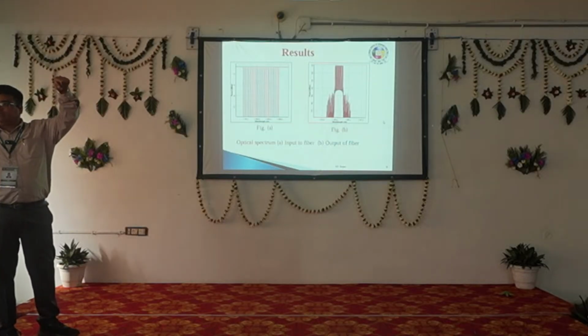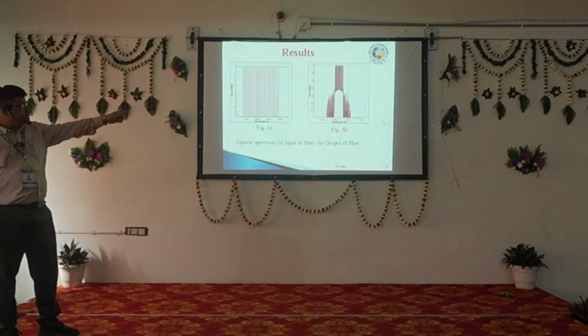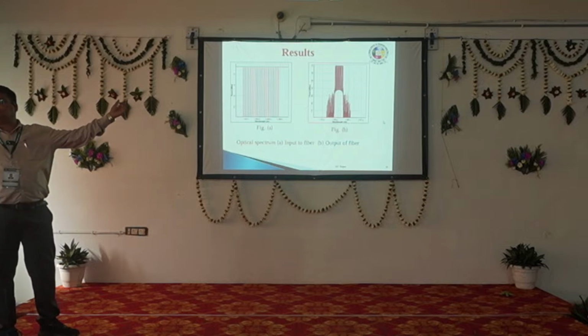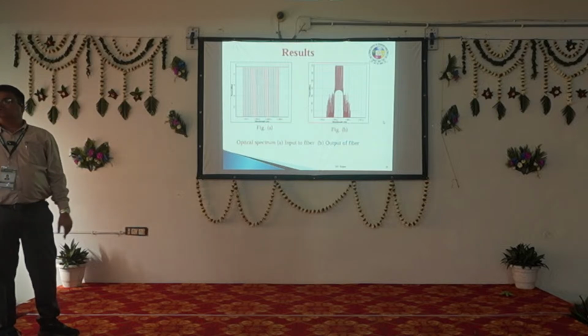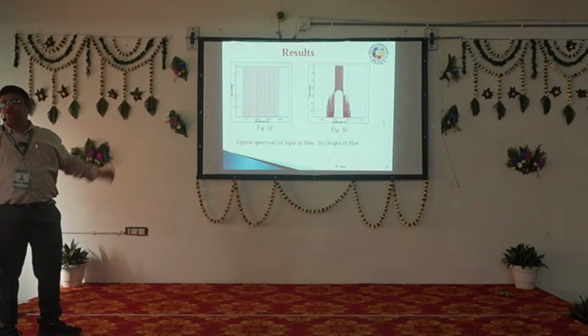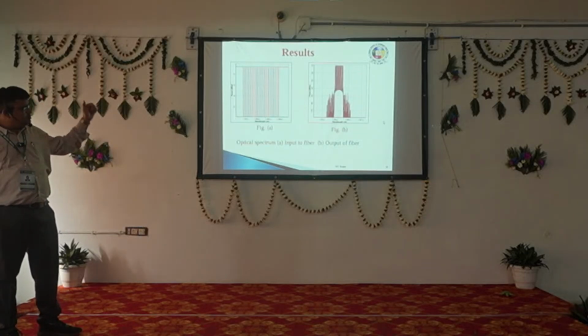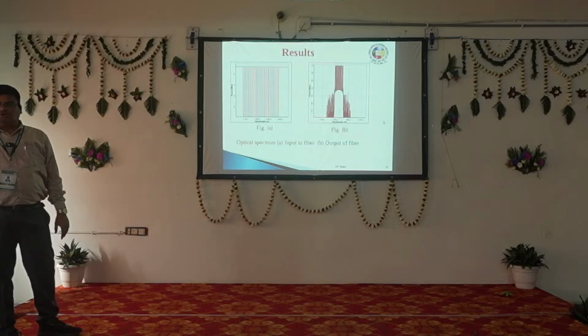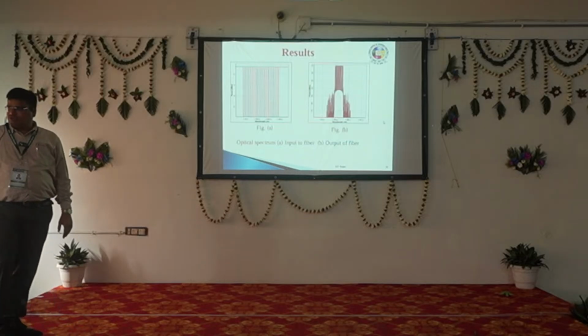That is 64 squared into 63 divided by 2, as per the equation. And you can see the spectrum here. The spectrum looks like so many other signals overlapped with the original signals also. Did you get it? No doubt the sidebands we can eliminate by using filters. But whichever is overlapped with the original frequency, there the SNR will be drastically reduced and BER will drastically degrade. Am I right or not? So that is why the question is how to improve its performance. That is the challenge.